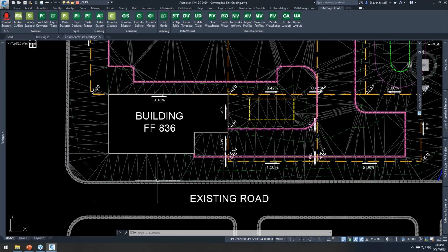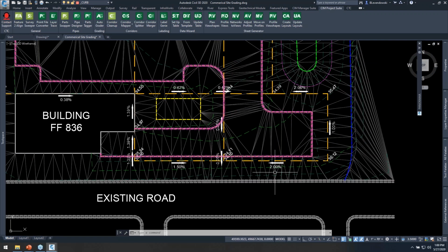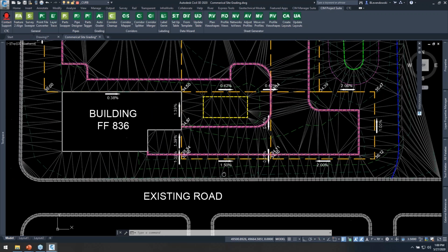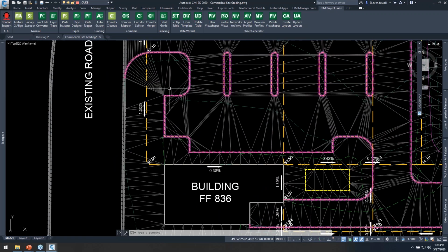So I think what I did here is what you were after, right? So it's not so much a daylighting, but it's a matching into a predefined grading limit. You do like I did here. You just grab those feature lines, draw them if you don't have them, and add them in. But there's nothing like really to automate there, right?